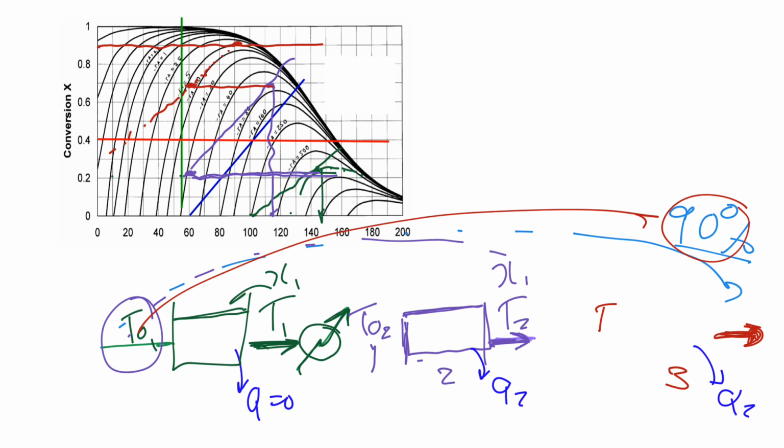That is now fixed. It is not something that I am going to specify or choose, because it's fixed based on that maximum operating rate and the adiabatic energy balance. So I now know what my inlet temperature to my third reactor must be in order to minimize the amount of catalyst that I use in each of these reactors.